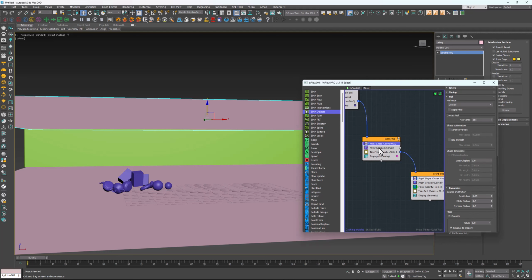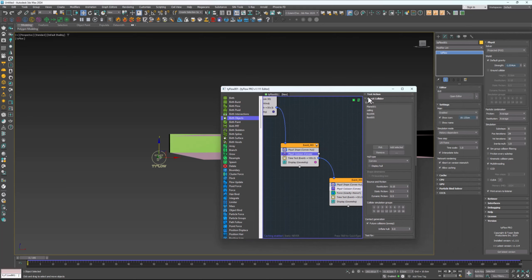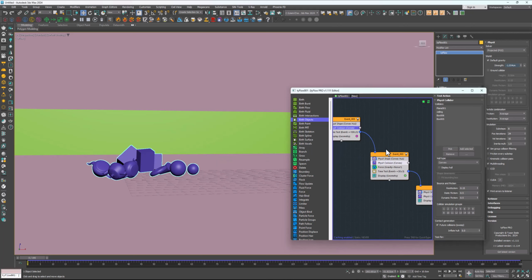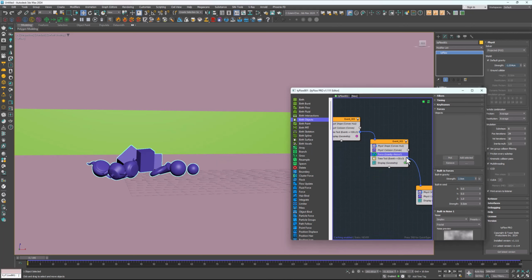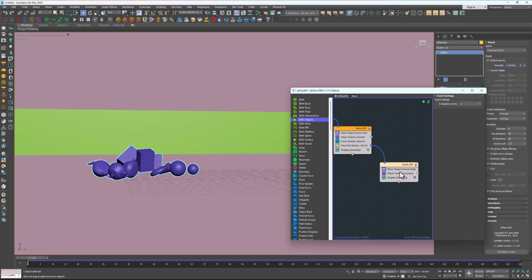If we use physics shape and physics collision with no force, it will use the default gravity of the Tyflow setting here, and you can see here, yes, the default gravity is checked on. And after that, again, we have no gravity with positive value. It means that we have no gravity. And again, we use time test to send the particles to another event.